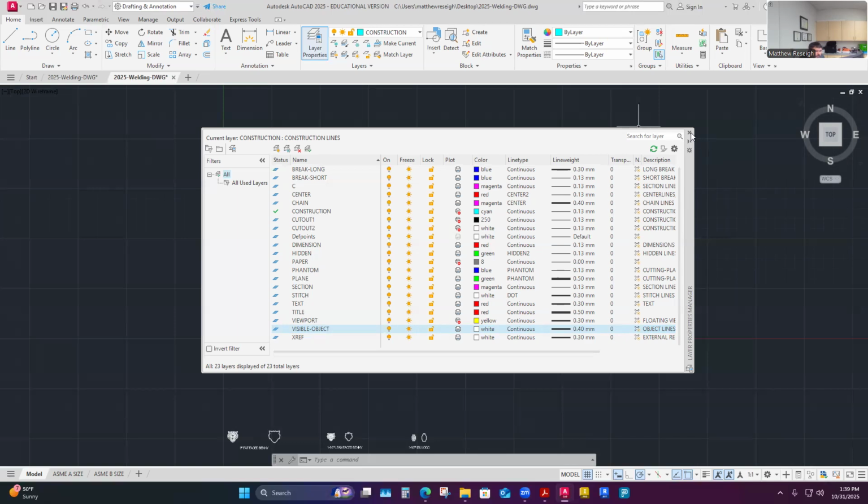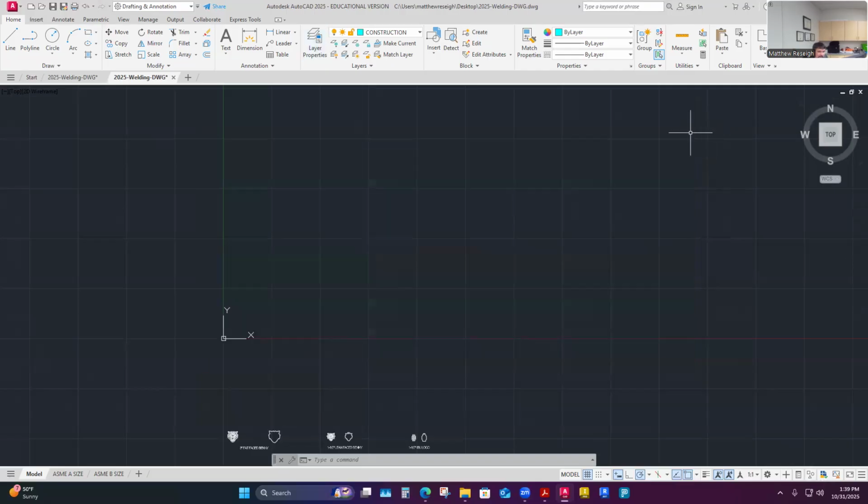Anyway, that's a little in depth on why I even have layers, right? A DWG file is usually this really saturated type of file with lots of line types, lots of layers doing all different kinds of things. That's where we do most of our drawings, and we have the most data-saturated drawings. And then our output from this is going to be that DXF file type that the machine is going to cut. And it's just going to be a single layer.